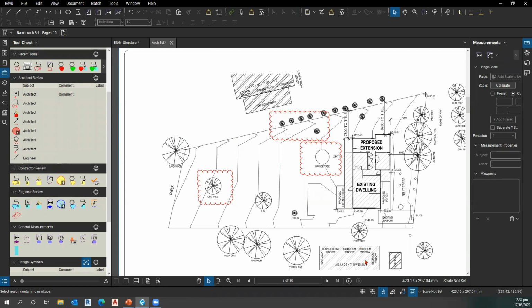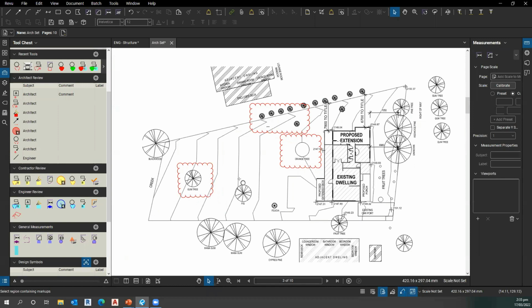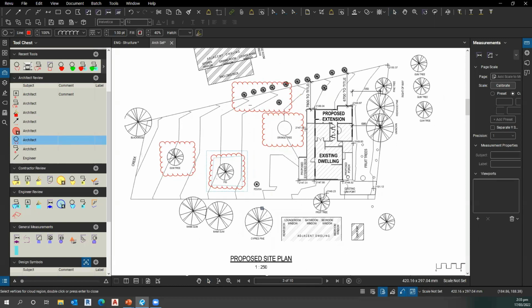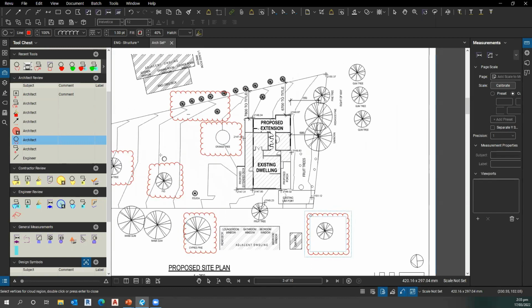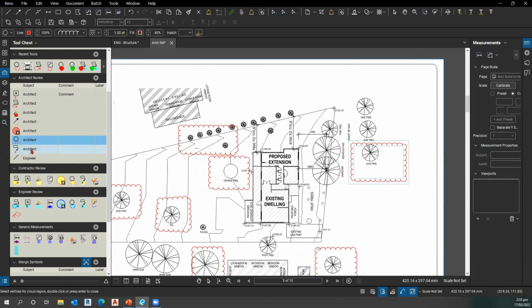What you can do is turn on the reuse markup tool, and see the difference. I'm going to turn on my cloud icon again. Boom. 1, 2, 3, 4. I'm not wasting any time going back and forth. This works for any markup, not just for cloud. I like using the cloud example, but you can do the same thing with something like text.